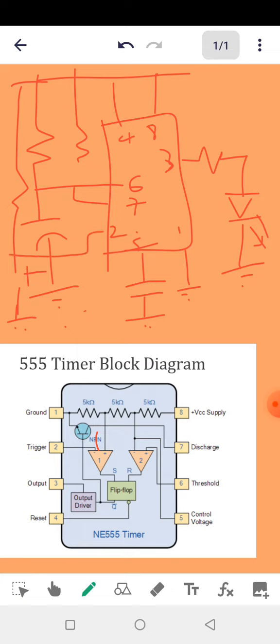Now when you set this up, what happens the first time is your 555 timer will come on for a time period that has been set by this resistor R and this capacitor C. This other resistor here is just to limit the current that flows through that line for your reset button. I think it's awesome when you connect your reset button like that.